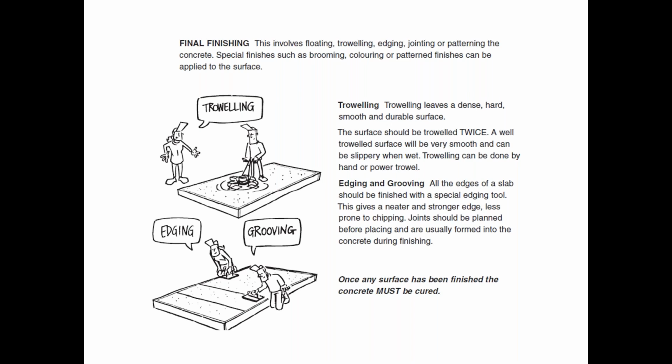And you need that on the surface of the concrete, especially if you're going to have cars and trucks driving over the top, or if it's concrete in the house and a lot of people walking on top of it, you want it as strong as possible. And then down the bottom, once you've got it nice and strong and dense, they'll put in some grooves sometimes and finish off the edges to round them a little bit so you don't have any sharp edges.